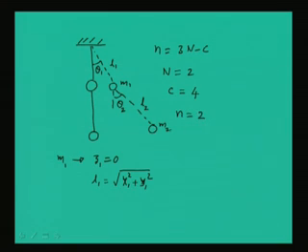So, with this simple example of a 1 degree of freedom system and a 2 degree of freedom system, we have shown how the degree of freedom can be obtained for a particular system, but the similar concept can be extended for a larger number of mass systems.